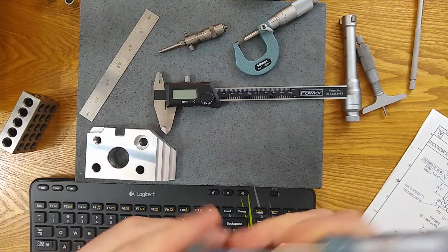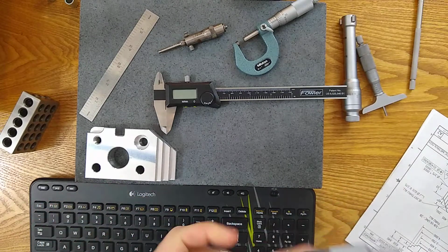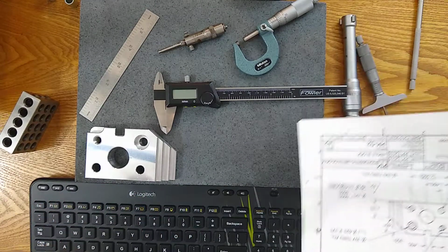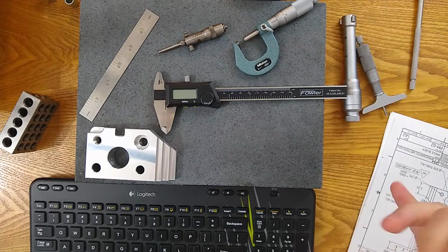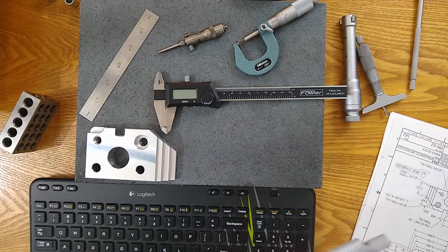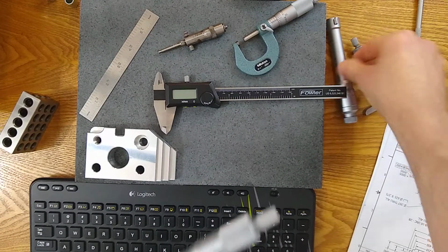It really goes into the details of when you can use these tools and when you can't. So with that knowledge, it helps you filter out, oh yeah, I've got a tight tolerance zone, can't use calipers. I've got a tight tolerance zone, that's internal features. Maybe I want to use pin gauges. Maybe I want to use a 3-point hole mic. So it can help you narrow down your list.